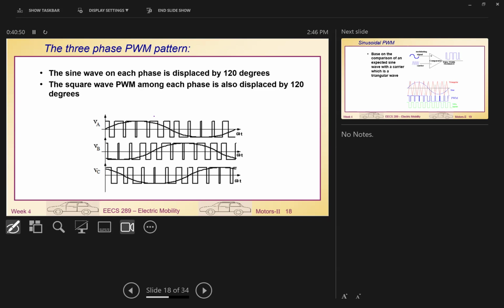In many industries in the past, they tended to seek more energy savings, and they tried to use inverters to replace all the sine wave operations. Once they changed to the inverter, the motor got hotter because they're using PWM. So in this case, you need to ensure your motor will survive PWM. Some motors are not really good for pulse voltage because it generates high dV/dt.